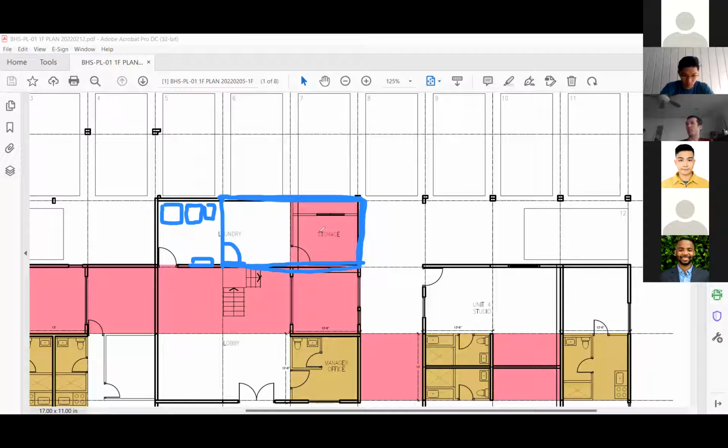But we just need a pretty comprehensive list of materials that we're going to be using for the house, the building envelope, and some of the wall spaces, because those go into the calculations for how much heating and cooling you need, which is ultimately how I can size the geothermal heat pump that we're going to implement into the system.